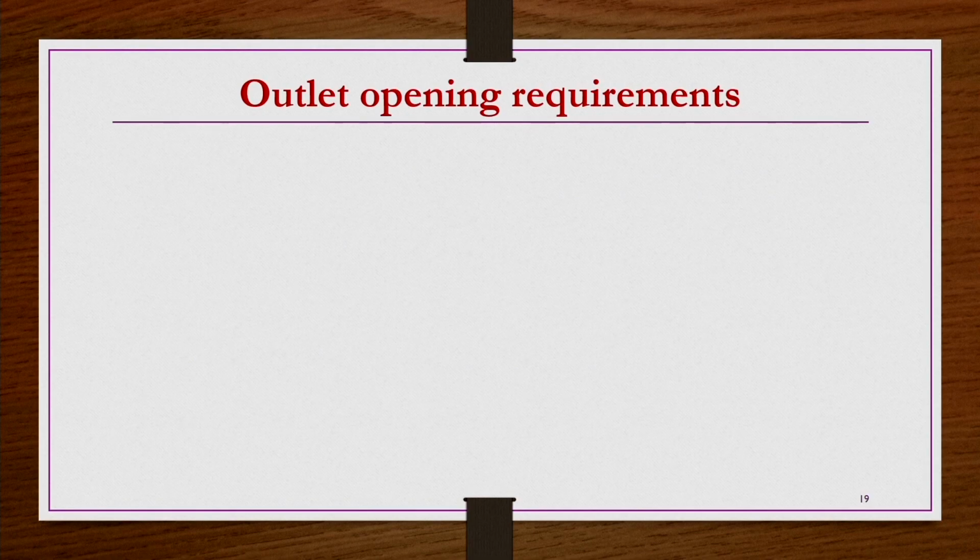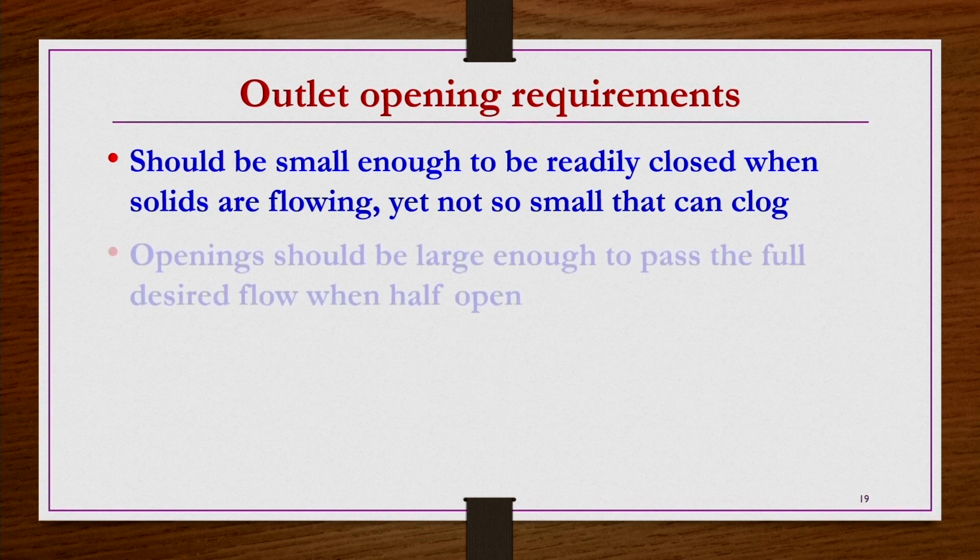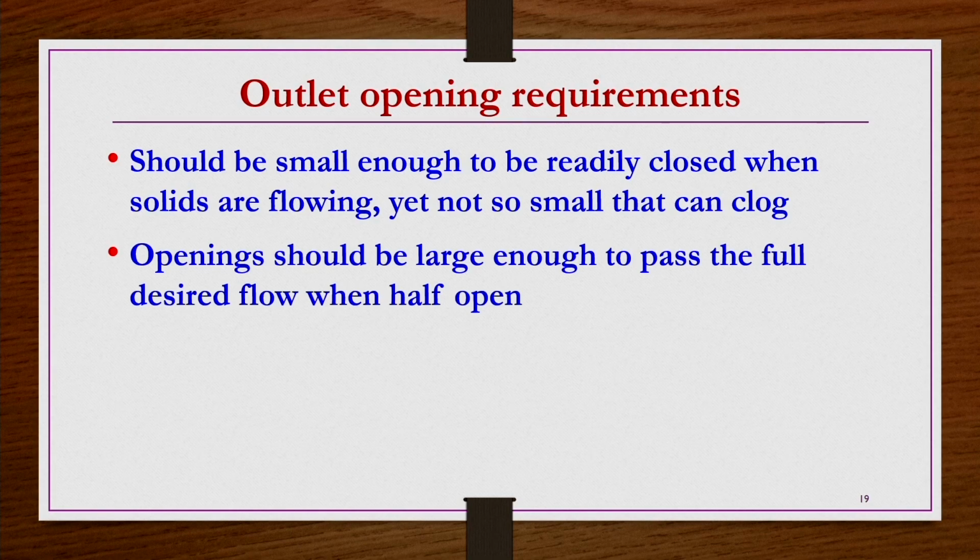Then what should be the outlet opening requirements? Specific outlet requirements should be calculated based on the design concepts, but in general, what you expect the outlet to do is this: it should be small enough to be readily closed when solids are flowing, yet not so small that material may clog, but the opening should be large enough to pass the full desired flow.